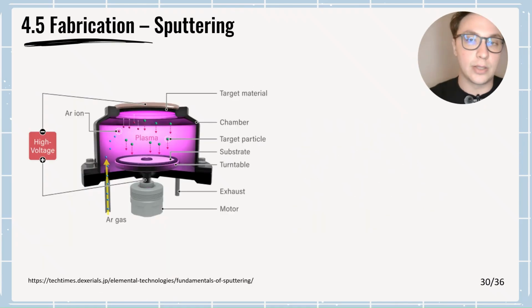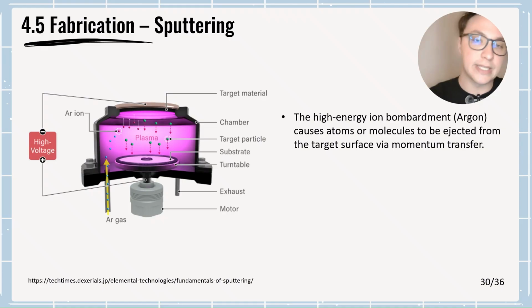Another, the final fabrication process I would like to mention, that I personally investigated during my PhD, is the sputtering process, in which basically we have a high energy ion bombardment in an argon environment, under vacuum conditions.